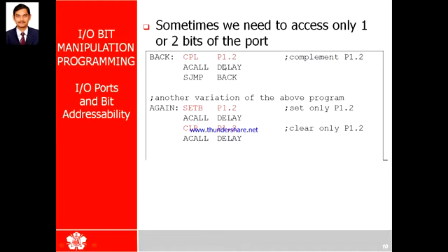So this can also be written by using instructions called setB and clear. Instead of CPL, I can replace the instruction CPL. Instead of that, setB clear can be used. So you can observe here setB. SetB stands for set bit. What are we setting? We are setting port 1 of a second pin. Assuming here if it is connected to LED, then LED will glow by setting this.